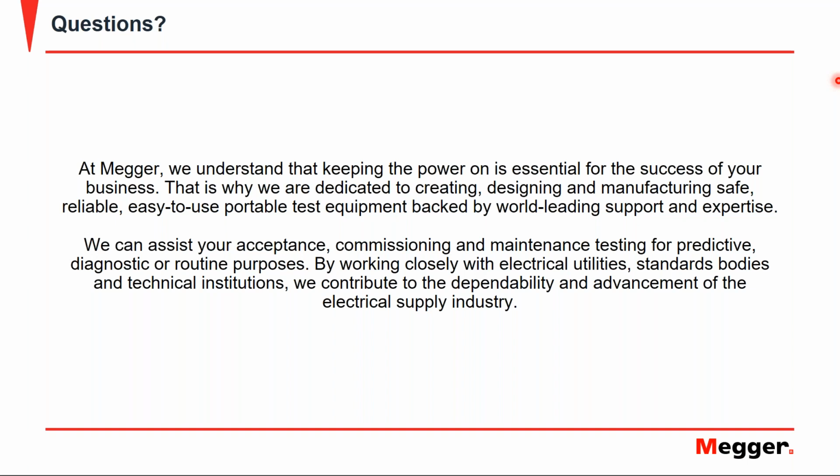That's a really good question, and I think I know where this one is coming from. When I said around 1 nanocoulomb, I meant that's the discharge that you can expect. As Hein was mentioning earlier, it depends on the defect and on the cable. PILC is obviously going to be much higher, at several nanocoulombs. But with XLPE or EPR, you may expect defects more in the hundreds of picocoulombs.